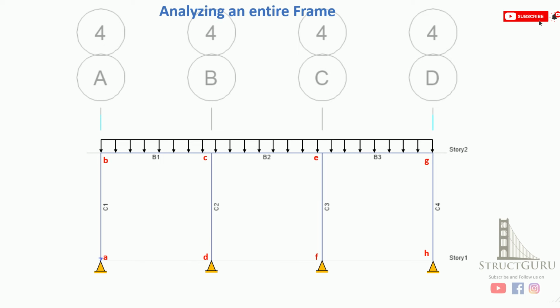So assign the loads which we have computed in the Excel sheet, and the magnitude still remains the same, which is 1.70 kip. You might be thinking that solving this frame would be a bit cumbersome, but it's not, because if you analyze, this frame is symmetrical, and if you solve half of this frame, you will automatically get the answers for the other half. For example, if you are solving the left hand side, you'll automatically get the answers for the right hand side.